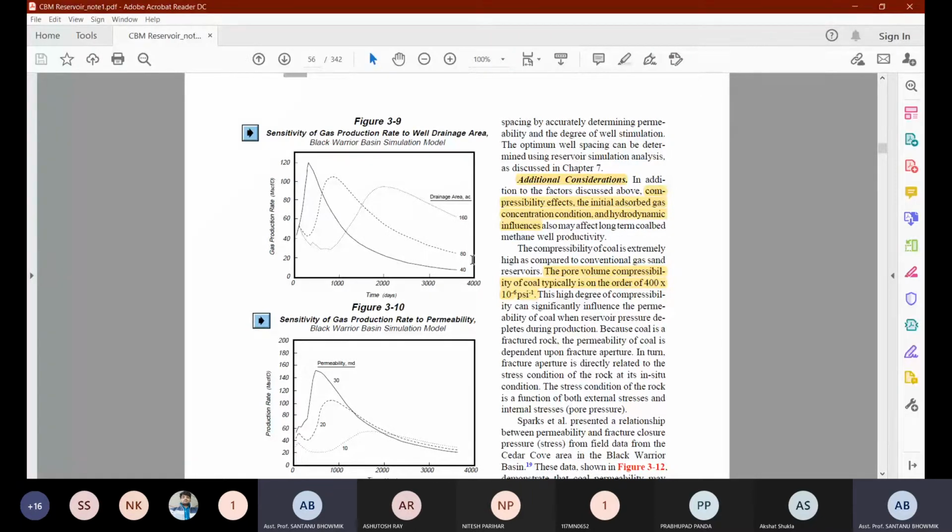That means the gas production will be much more delayed because the total water production content is very high as the drainage area becomes higher. And then accordingly, when the water reduces, you will see that the relative permeability phase will begin, and so the gas production rate will gradually increase, and then finally it is going to decrease.